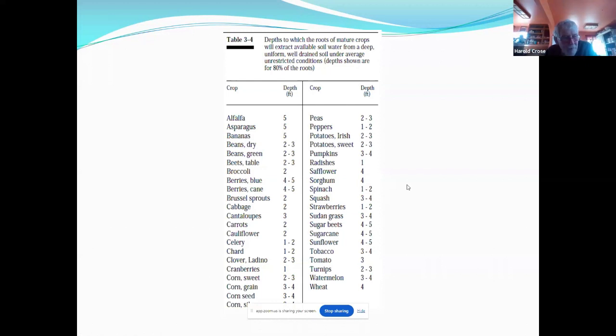And then I stop them and say, is that the only crop you're ever going to grow? And if they say, no, in 2 or 3 years, I'll be growing alfalfa. Well, that's a whole different root growth. So you have to look at the entire rotation, what they're growing in, and you need to design for the most critical. And I say you design the most critical for water application for the crop with the most demand, but you develop your water management plan for the least. Does that make sense? I hope.